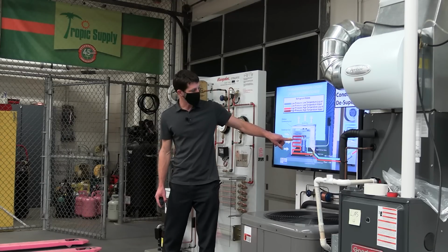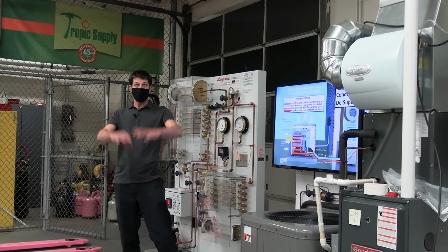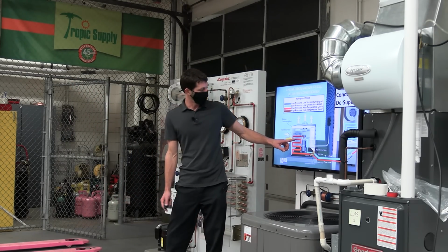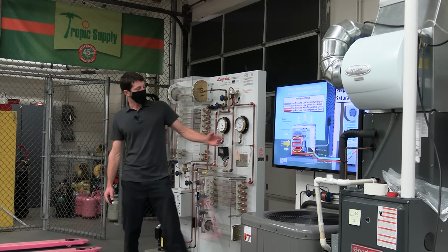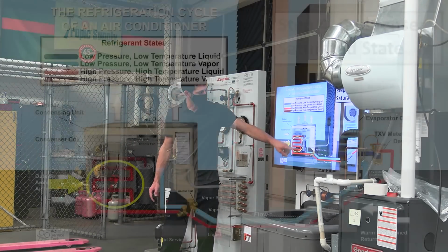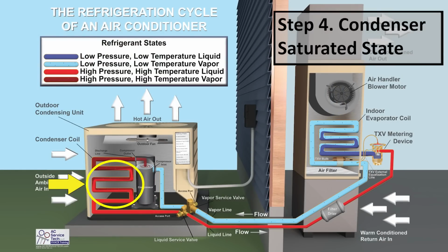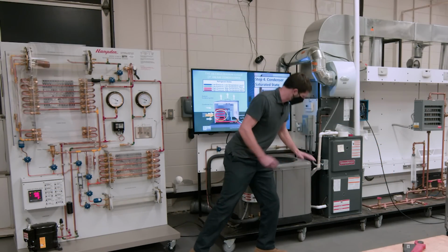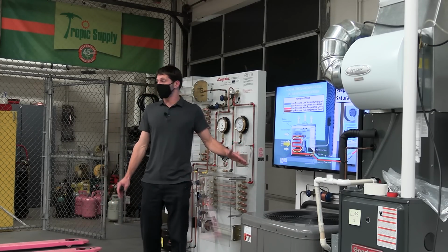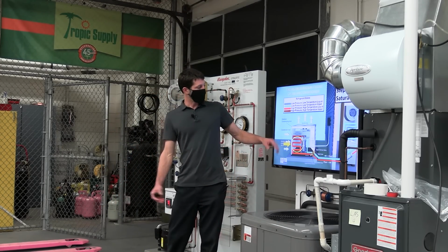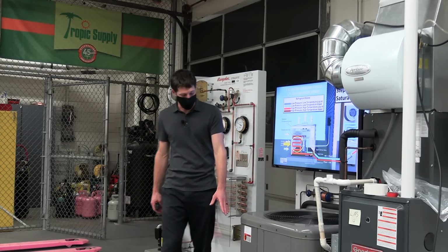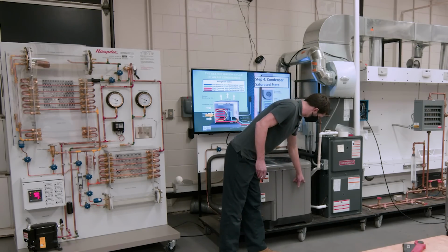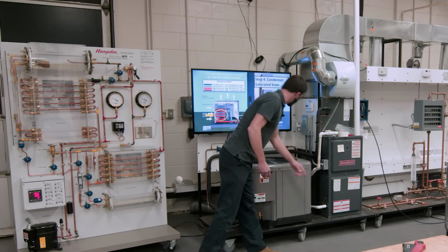It's then lowering in temperature because it's in the vapor form, like a gaseous state, until it gets to right here. And that's when you are turning into the saturated state. And once it hits this point where you have liquid and vapor existing at the same time within each of the tubing runs, it's going to stop falling in temperature. It's going to stabilize. And so that might be maybe at, say, 100 degrees. Maybe it's a 100 degree saturated state as it's flowing through here.